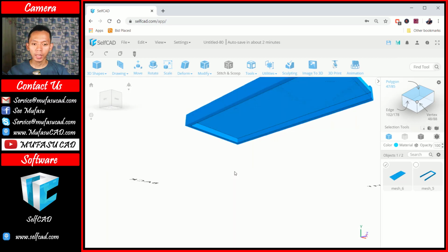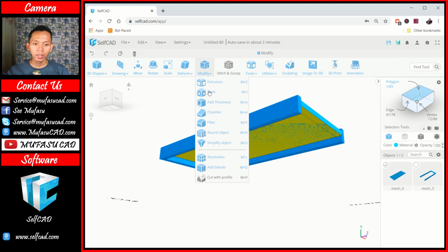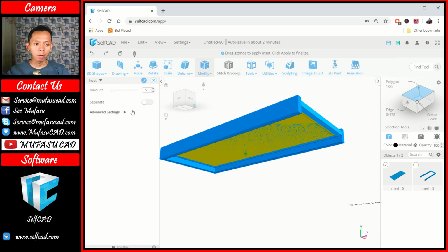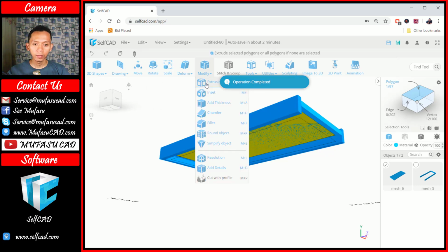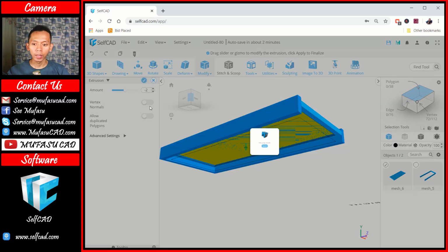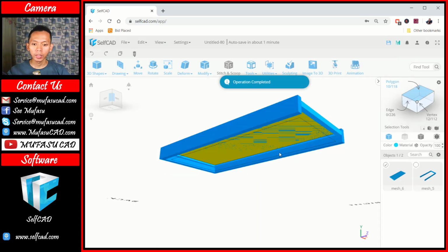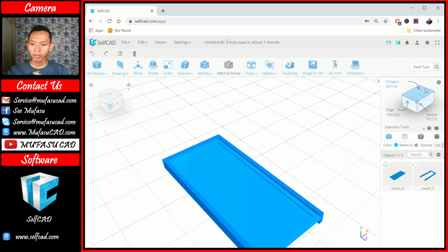You also can select at this face and then we can use insert again with amount 5. The next we can use extrusion. We set -2 and you can click OK to apply. So we already extruded this face, also this face. You can uncheck this polygon option.